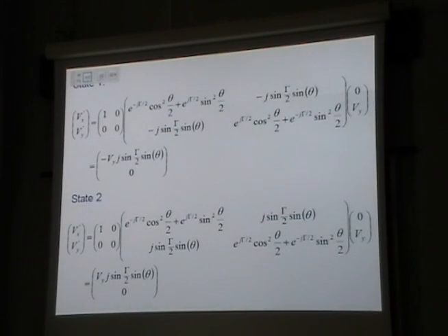So the ferroelectrics can be both intensity and phase modulators, just depending on how you orient them and how you design them. You can also do other things I don't have time to describe now. They're a very versatile and useful way of getting access to an optical system, and you can analyze it using this very simplistic view of the crystal molecules, purely as birefringent objects with different orientations, which can be varied by electric field. I'll stop there.